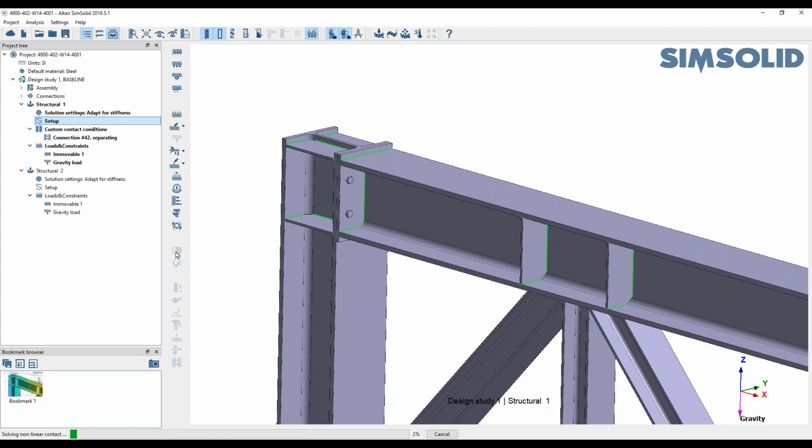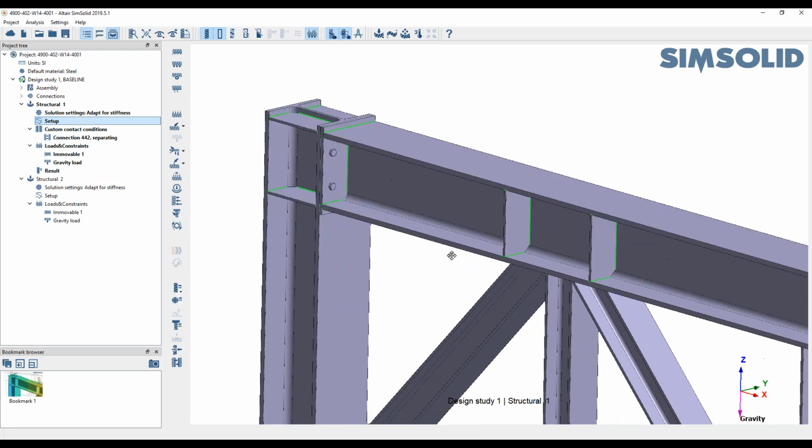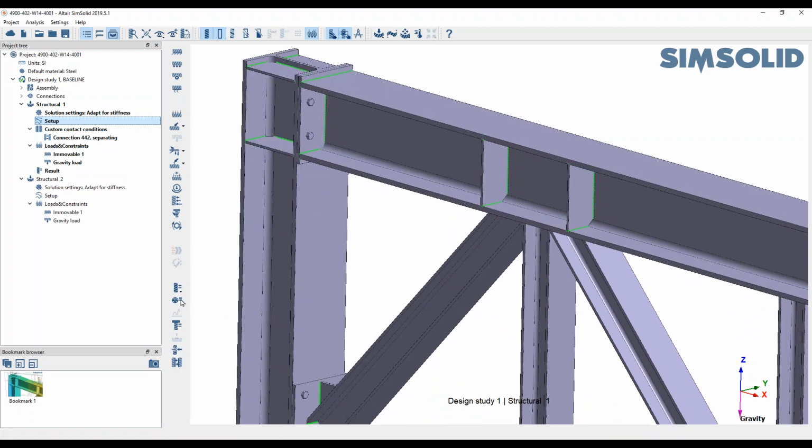So in something like this, there's about 6 plates. We would pick all the 6 plates and then change the contacts from fixed to separating, and then run the simulation again. Now the separating is a nonlinear contact, and obviously like Nastran, it does take a little while to run. Now because we already run this analysis, the second time run should be a lot quicker.